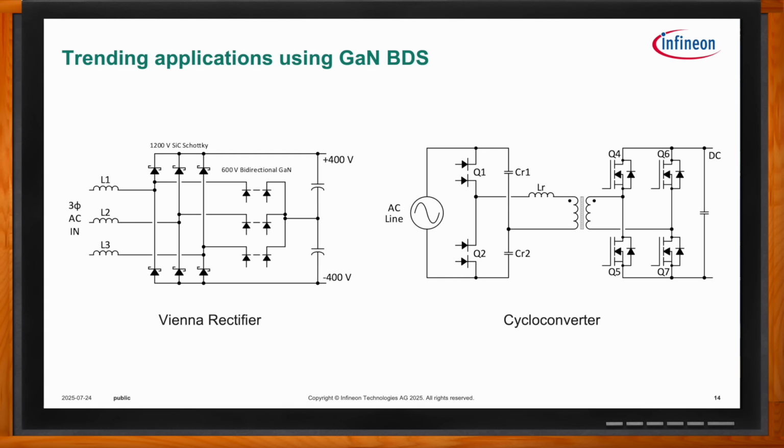The first thing is that GaN itself doesn't avalanche like a traditional power transistor. Take the example of a 600 volt rated power transistor, a MOSFET. It will avalanche somewhere maybe 680, 690. It turns into like a Zener diode there, which can be good. It depends on the application, but it also means at that point, the voltage can't go any higher and it's now dissipating power in that mode, and it can only do that for a short time.